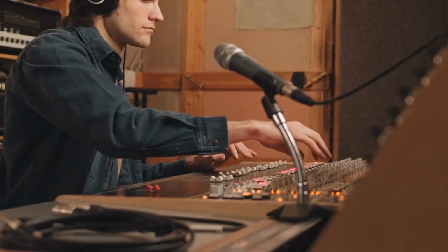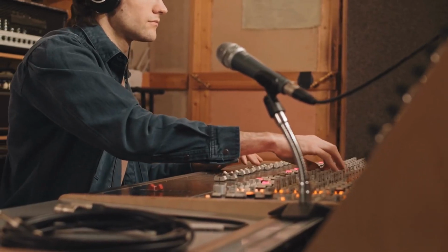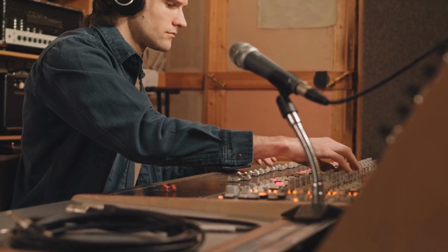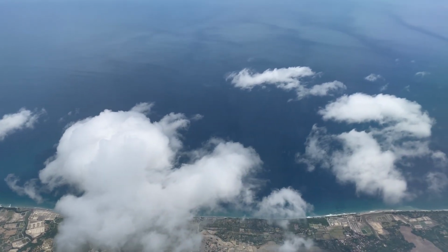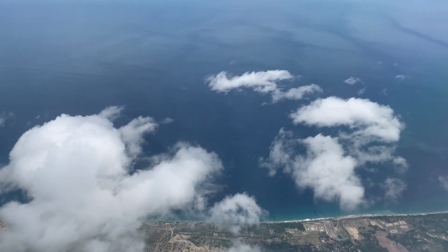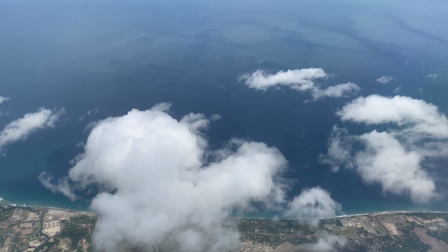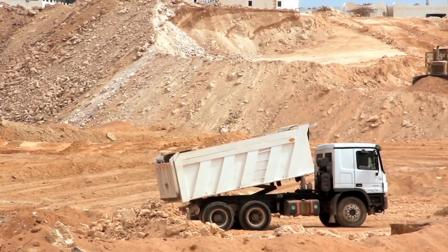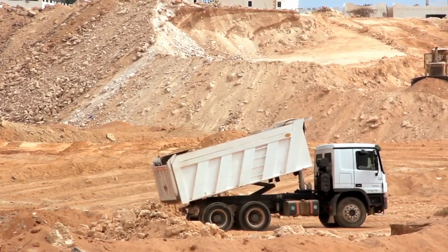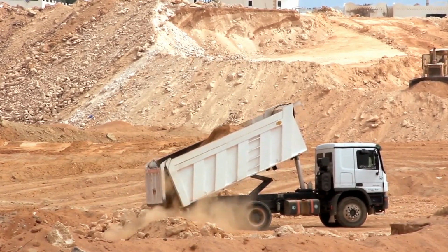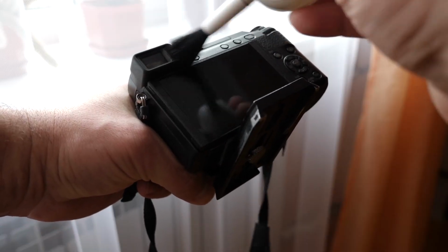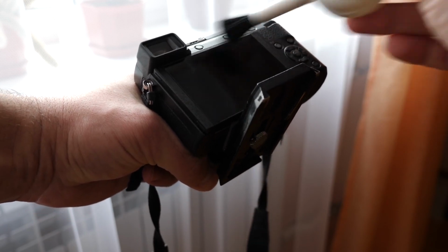Ground loops, which occur when multiple devices in your setup are grounded differently, can cause a low-frequency hum in your recordings. Using a ground lift adapter on one of your devices, or ensuring all equipment is plugged into the same power strip, can often resolve this issue. If the problem persists, consider using an isolation transformer or DI box with a ground lift switch to eliminate the hum. Maintaining your equipment is also crucial for preventing issues before they arise.